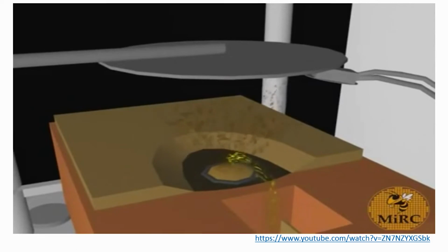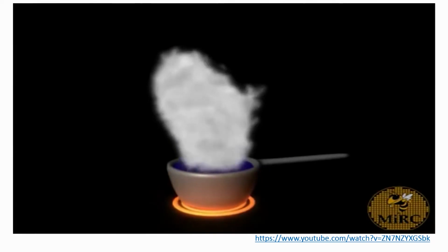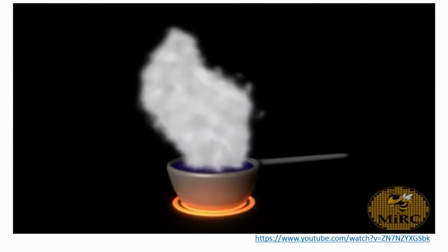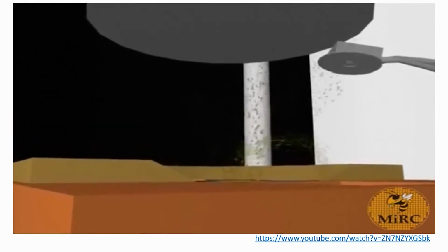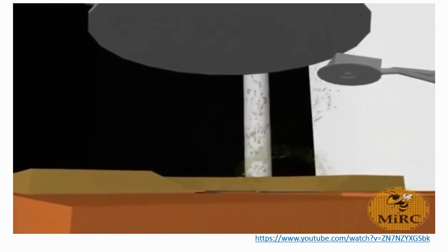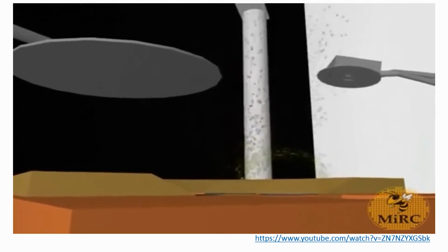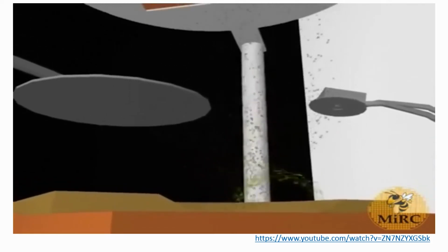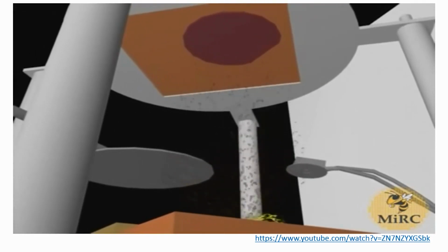The metal then heats up and begins to evaporate onto the shutter. This process can take several minutes. This is similar to a pot of boiling water on a hot stove. A sensor within the chamber is used to determine the current rate of evaporation. Once the desired rate is reached, the shutter is open and the sample is exposed to the evaporating metal.